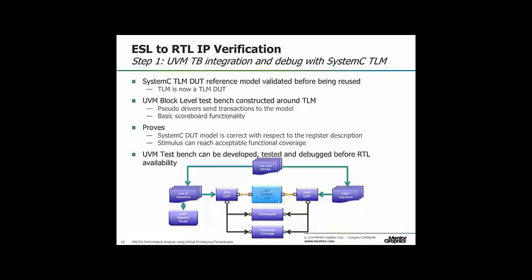So it proves that the stimulus is going to be sufficient to meet the coverage, and it also helps validate that the SystemC is correct and has implemented all of the correct registers that were specified. So it gives a nice head start to the people developing the RTL test framework.